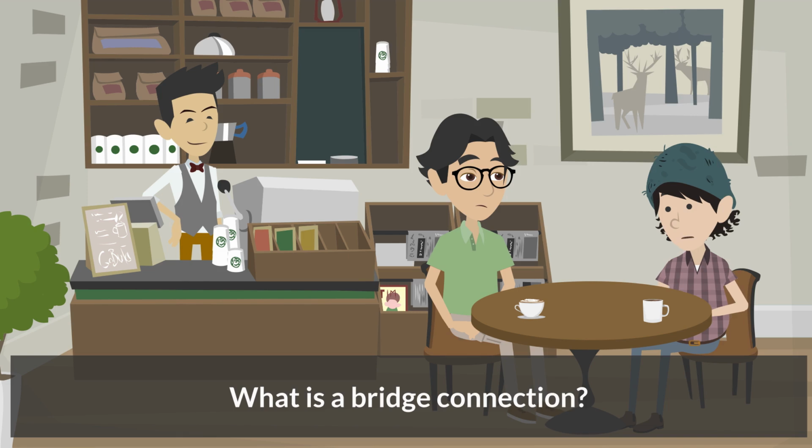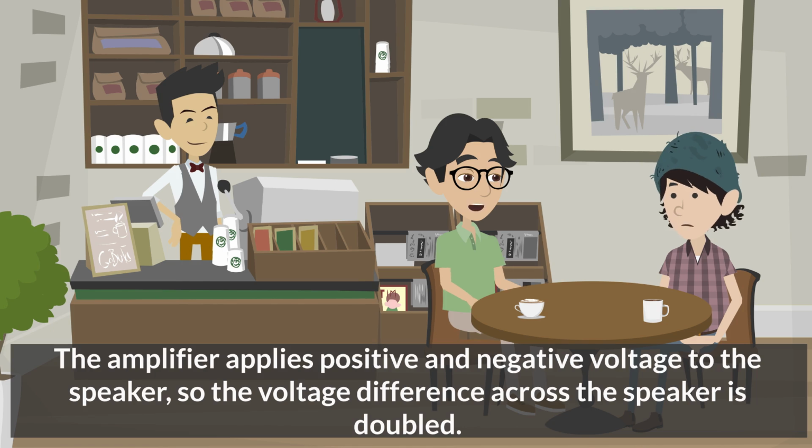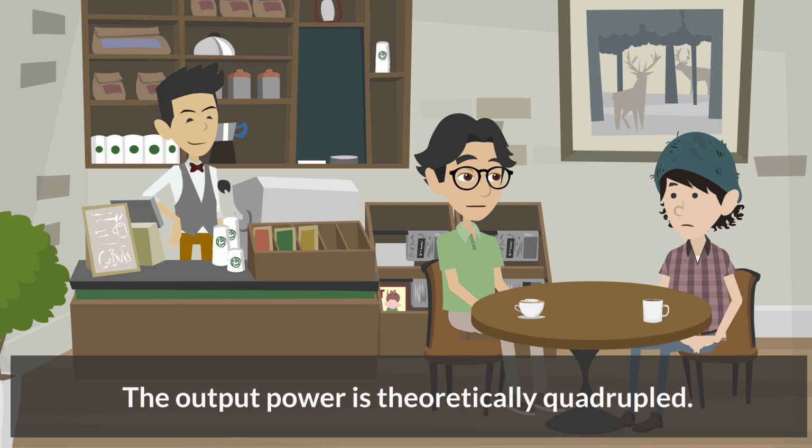What is a bridge connection? A bridge connection is a method of driving a speaker by outputting 2 signals, one input signal and one signal 180 degrees out of phase. The amplifier applies positive and negative voltage to the speaker, so the voltage difference across the speaker is doubled. The output power is theoretically quadrupled.